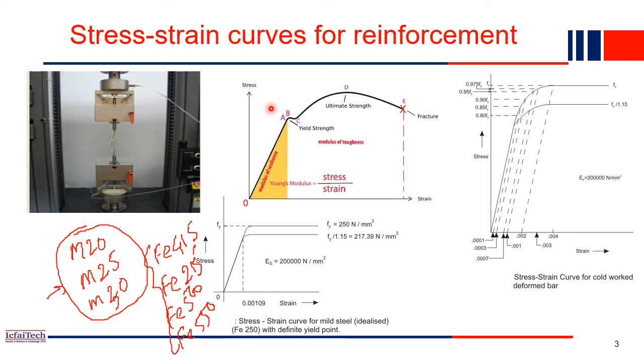Concrete, if you see, is made on a site, and it is made up of four different materials: coarse aggregate, fine aggregate, cement, and water. All these four ingredients may have impurities. That's why we have used the histogram. If you recall, in the last lecture we discussed in detail how to calculate the characteristic strength. We drew the histogram and found the characteristic strength. We considered a probabilistic approach.